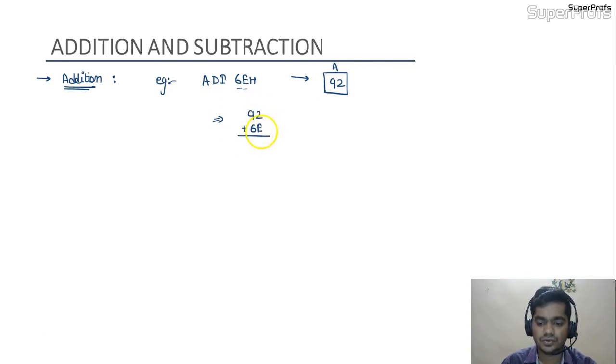So E plus 2 would be 14 plus 2, 16, and in hexadecimal format there is no value as 16. So from 0 to 15, then again 0 with the carry. So the answer would be 0 and there would be one carry present. So again 16, 0 would be the answer and carry would be generated. Okay, so this is our answer that is present inside the accumulator.